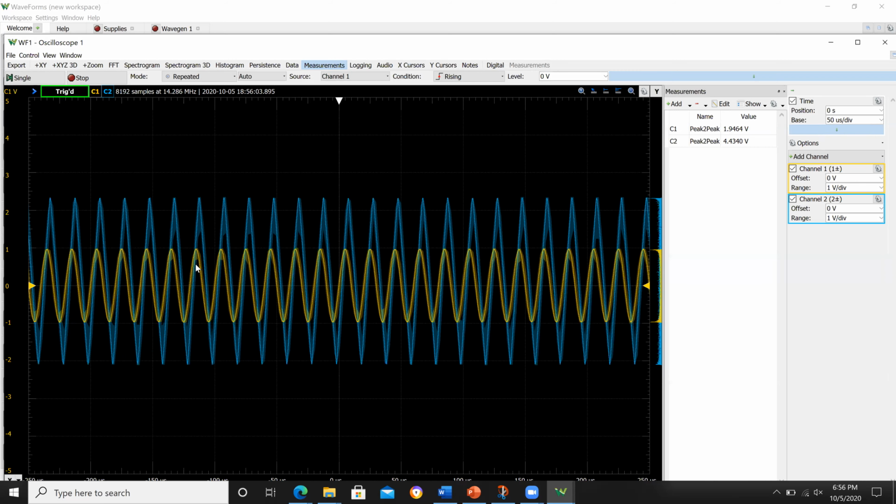So why is that? Well, let's go back. Remember some of the non-idealities of an op amp that we talked about? One of them being it has a limited amount of current that the output pin, pin 6, can source or sink. So current, maybe it's a little bit more of a difficult way to think about it, but let's just apply our thought process here.